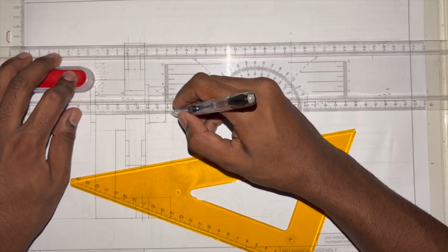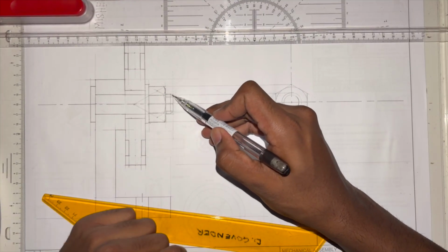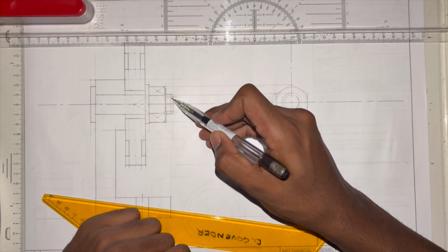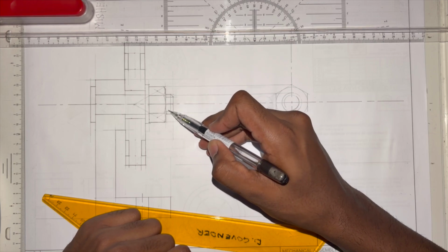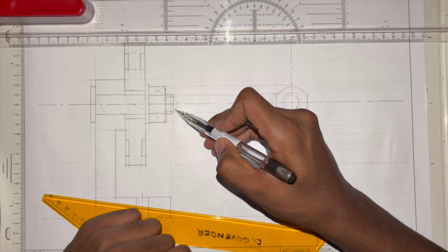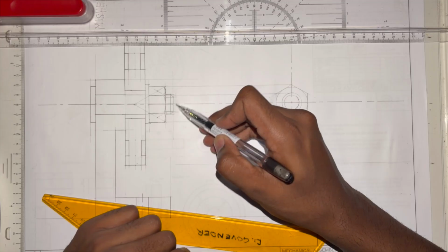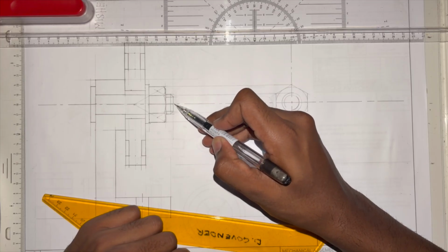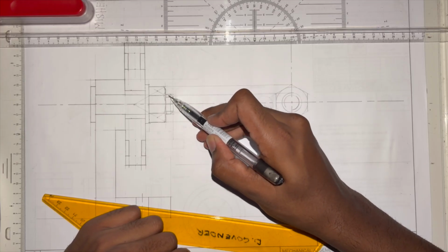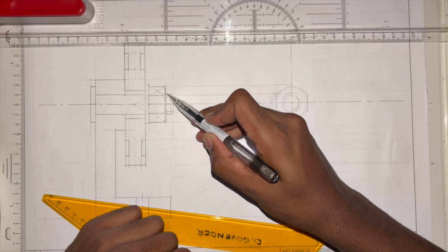Okay, this part is very important. You see all these things here, the end of the shaft with the 45 degree, with these lines here of the thread. Each one of these lines, as well as the 45, counts for a mark. There's around 8 to 12 marks, depending on which paper, which year, that are counted for this section alone. So don't skip this. Don't not draw it. Okay, and it'll always be shown here.